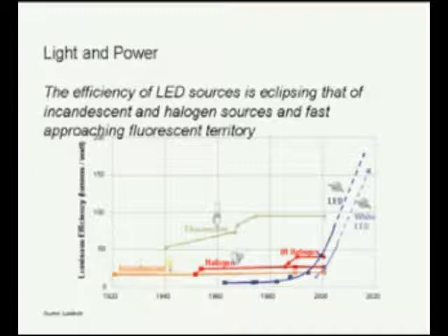Generally, compact fluorescents, those pigtail-shaped lamps that look like soft ice cream on a cone, are in the order of around 50 lumens per watt. Now remember that I'm talking primarily about source efficacy. Once you put these devices into fixtures or luminaires, then it's a different story. Much of the light can be lost in those devices because of shading and reflections and mirroring and diffusion of that light within the systems.